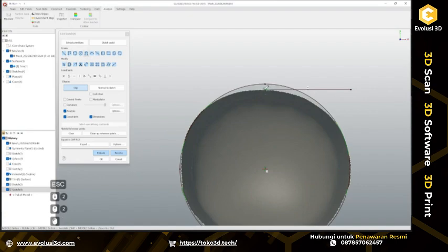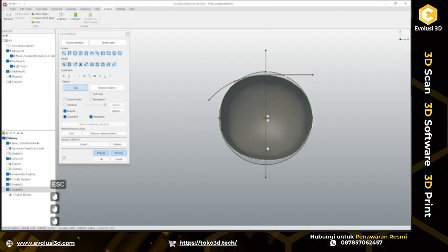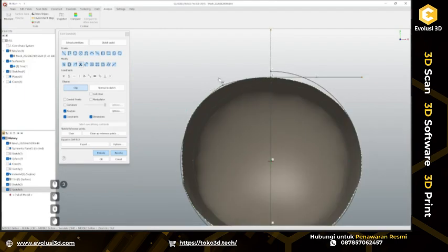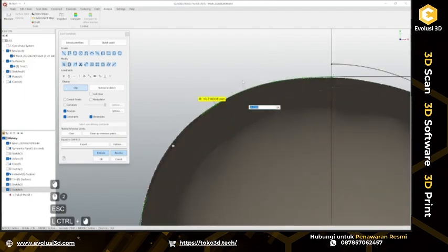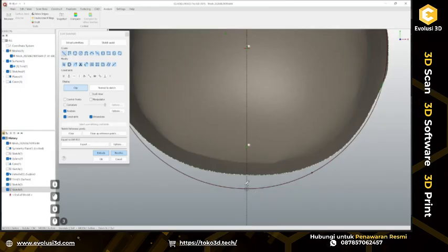Then I'm going to use a tangent arc to fit the top part of it, so I can see it doesn't bend good enough to complete all the shapes, so I'll just do that in parts. At this moment I want to create a vertical axis here, so I will trim this whole sketch later and just mirror to the opposite side. Okay, from here I can trim the circle, trim the tangent arc, add a calculated radius to this corner, and I want to do the same here on the bottom side.